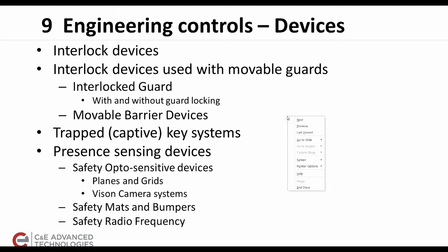Trap key systems are a methodology by which a given action will provide a key which allows additional function to take place. The great value of this is that one can very easily control the direction in which the operation takes place, and the sequence in which things can be done.